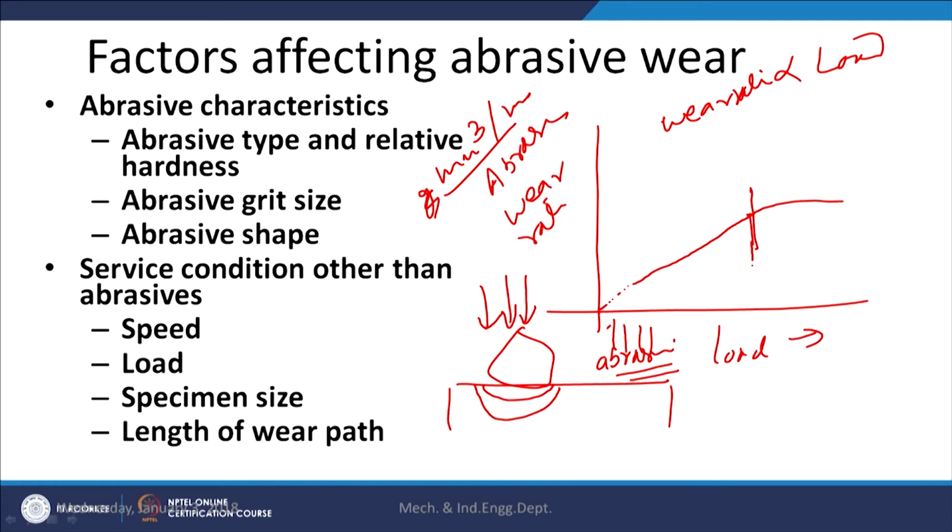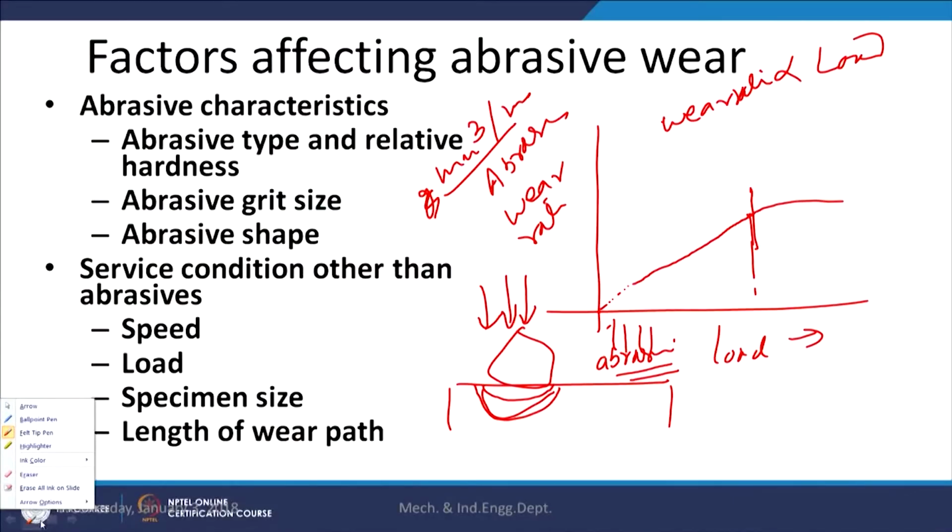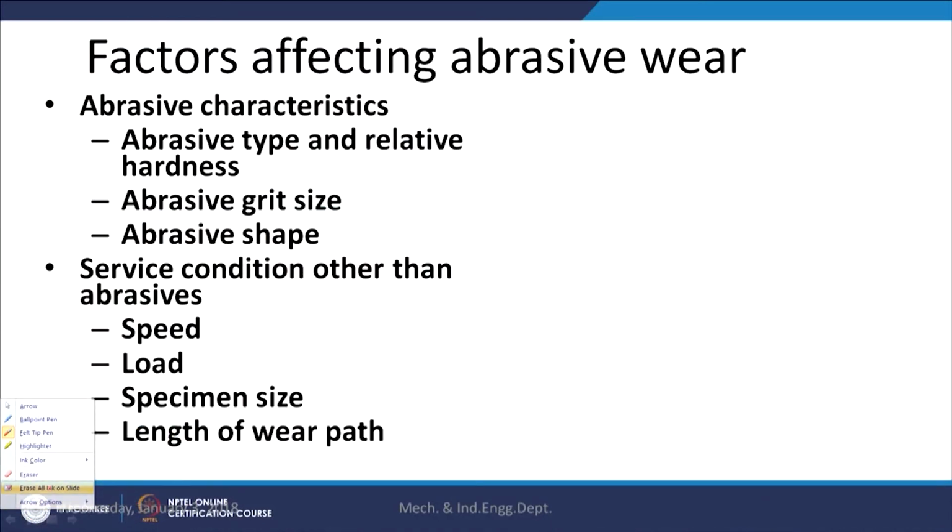This is the condition which suggests that damage to the workpiece and to the abrasives has started, and simply increasing the load is not causing much more indentation to cause the cutting and abrasive action. That is why an increase in load increases the abrasive wear rate up to a certain limit. Thereafter, further increase in the load does not increase the abrasive wear rate appreciably. Another important factor is the wear track length.